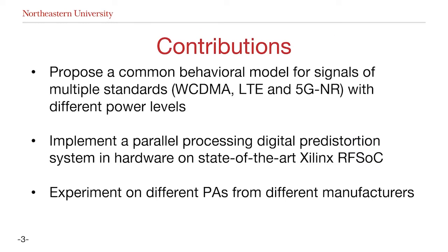For this work, there are mainly three contributions for the community. First, during our research on other DPD works, it seems that most of the work is focusing on a single standard signal, and their PAs are working under the same input power levels, so their models have limited flexibility. Hence, we propose common behavior models for signals of different standards, like 3G as the WCDMA signal, 4G as the LTE signal, and 5G NR signals, and with different power levels.